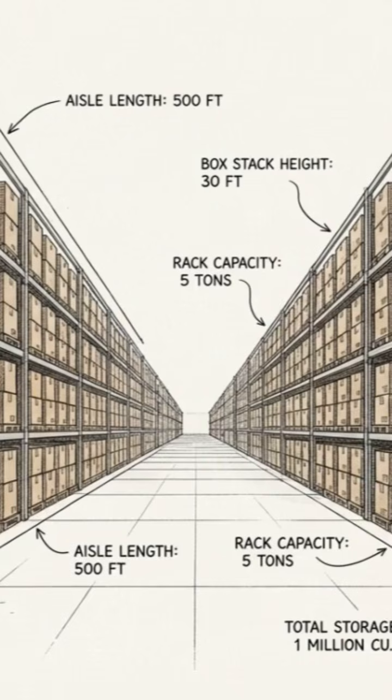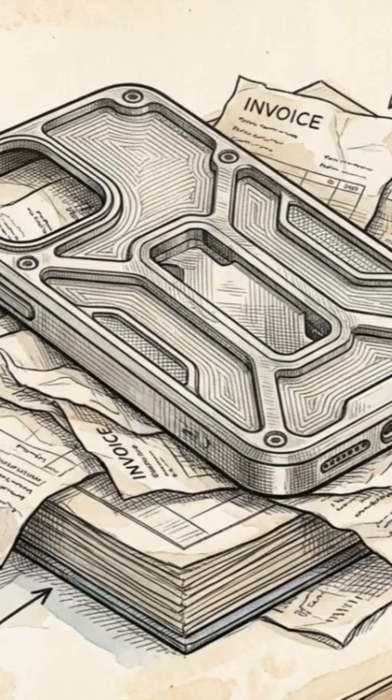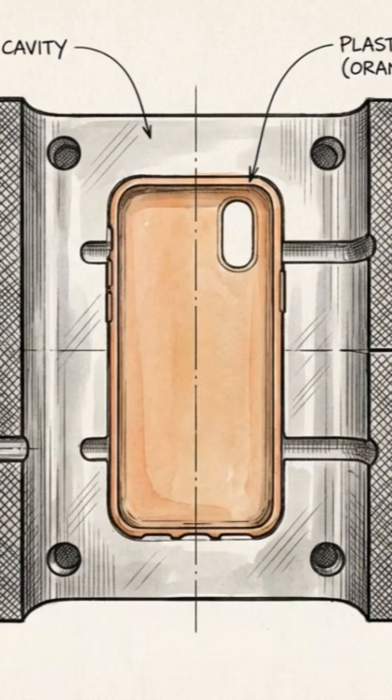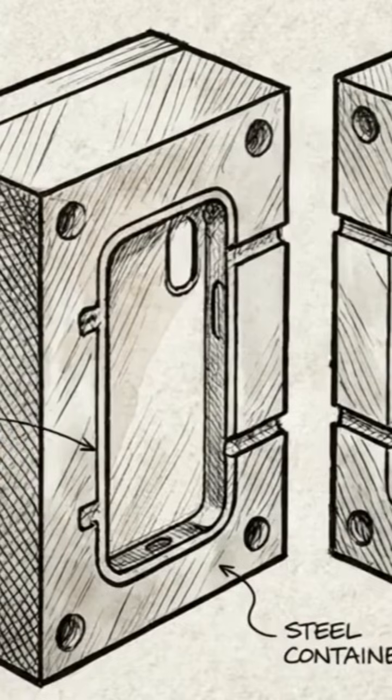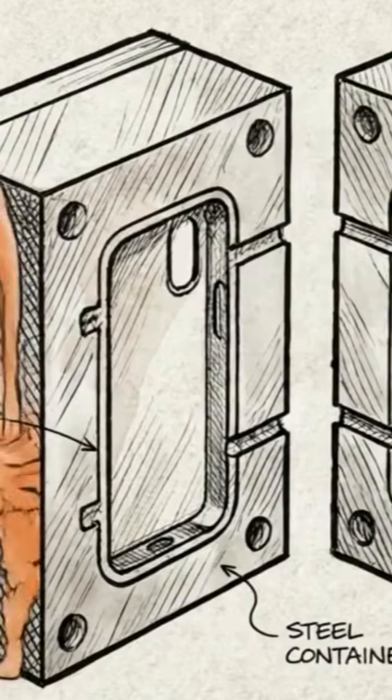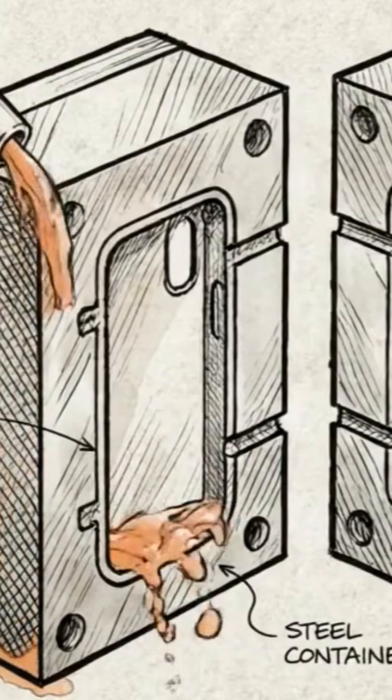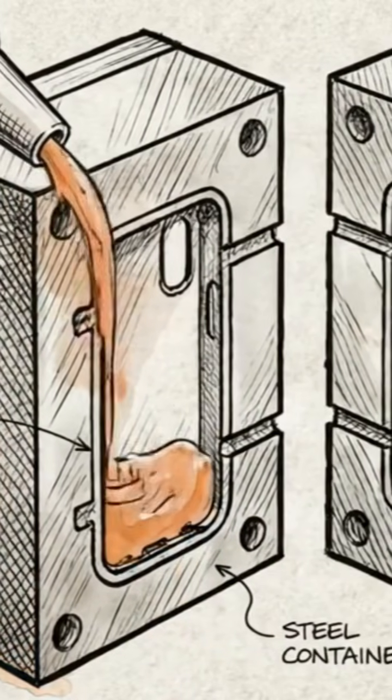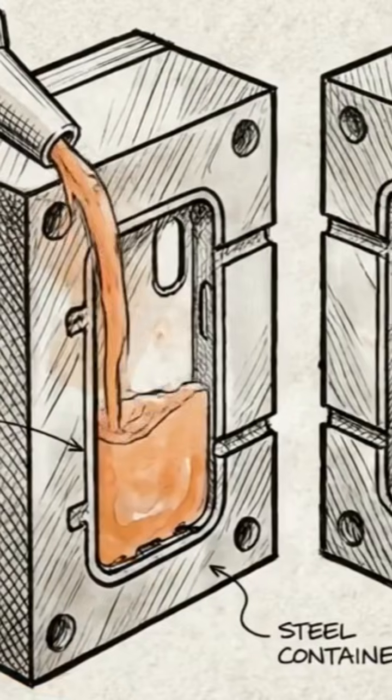But cutting takes time. When you produce 2 billion smartphone cases for a global market, carving them out one by one is far too slow and incredibly expensive. The solution to this volume problem is a formative manufacturing technology called injection molding. Instead of cutting material away, this process forces liquid material into a hollow cavity, letting it cool and harden into the exact shape you need.